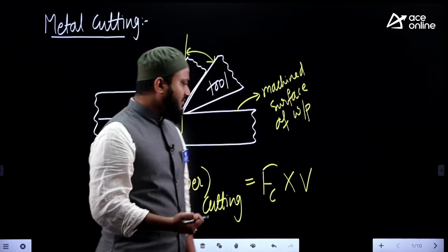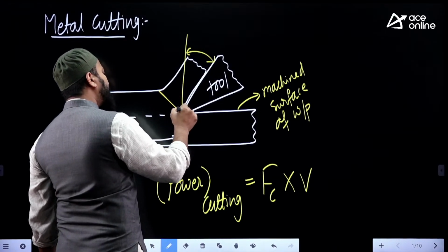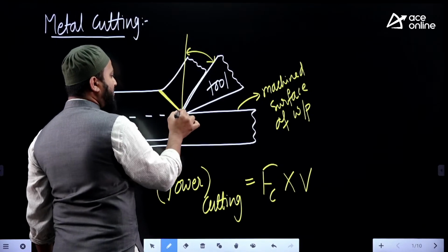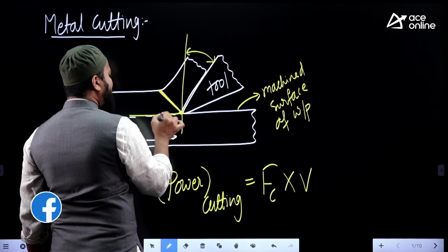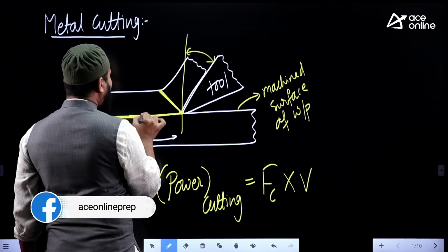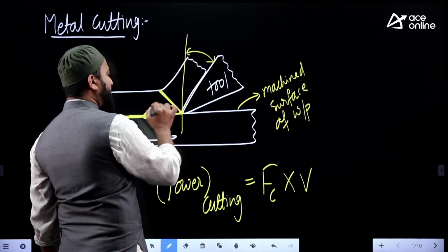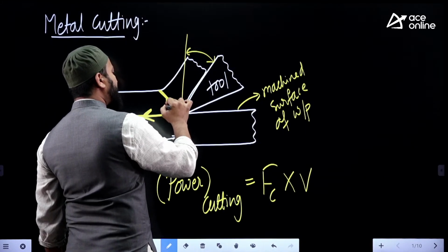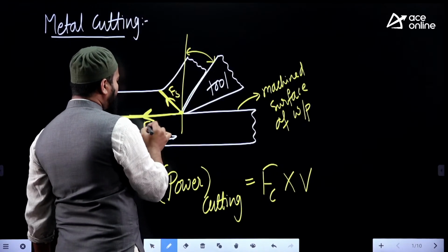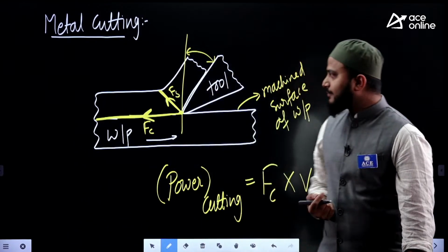The force is the shear force which we apply, due to which we try to separate the material. But to perform the shearing, the resultant imposed on the workpiece from the tool gives, in this direction, a cutting force. Or we can say cutting force is the measurable force, which is the algebraic summation of all horizontal components in this direction. Due to the dynamic nature of machining, we perform the shearing in this direction, where the shear force appears in this direction upon the cutting force. So shearing helps to separate the unwanted material.